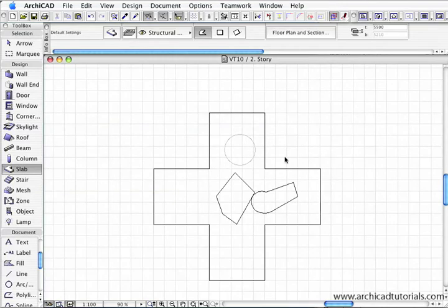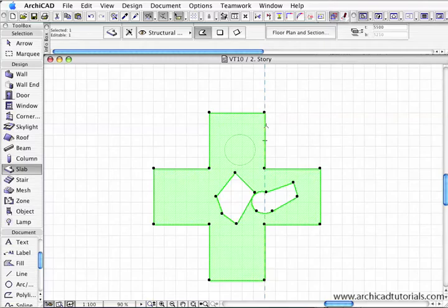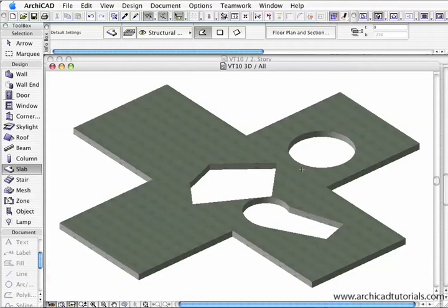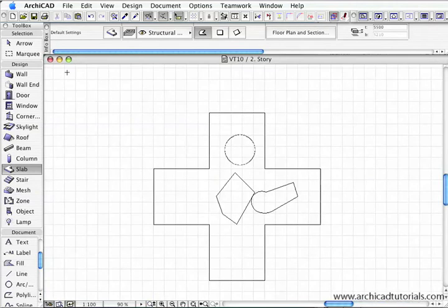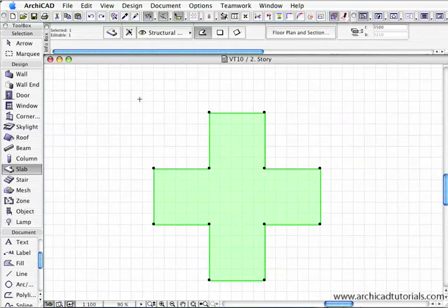Then if I click to the slab tool, hold the shift key, select the slab tool, then I'm going to hold my spacebar down, and as I hold the spacebar down, you'll notice that the cursor will change form so it looks like a magic wand. And the magic wand's got all lovely little sparkles around it, but as you go over the 2D line, it changes into a polygon type shape. While I'm still holding the spacebar down, I left mouse click, and it will cut a hole that will copy that circle that we've actually drawn. So if I deselect it and go to the 3D window, we can see that we've actually created a perfect circle in there. So I'm just going to close it off now and go Control or Apple Z and undo all those.